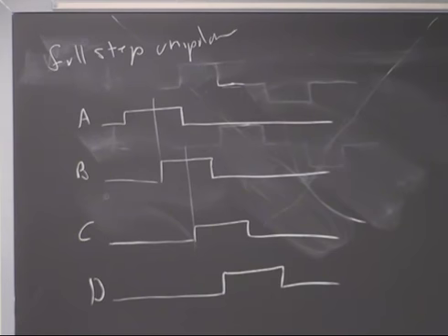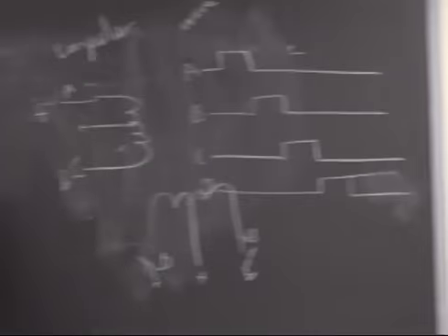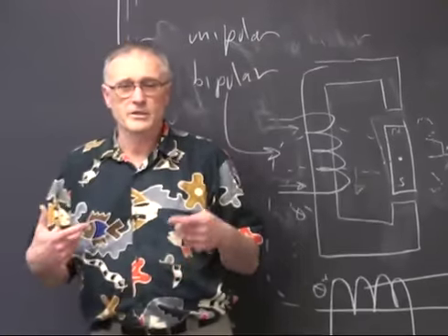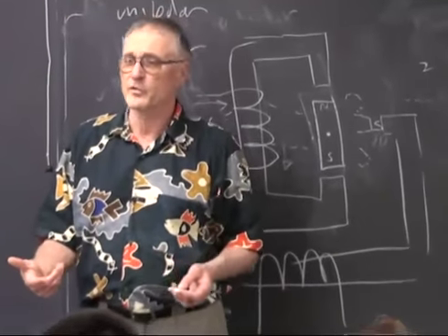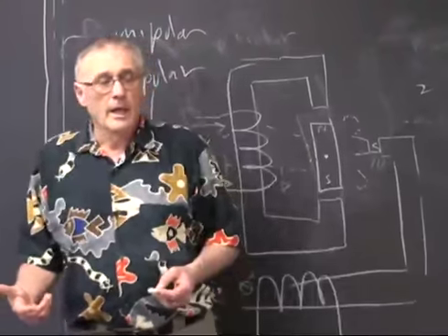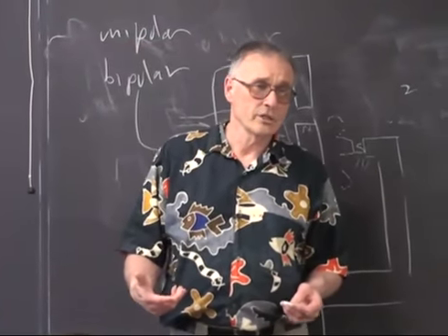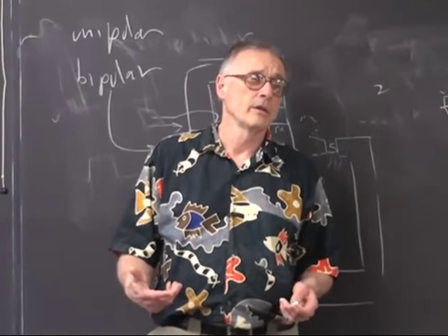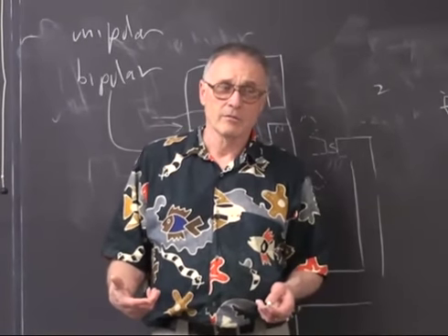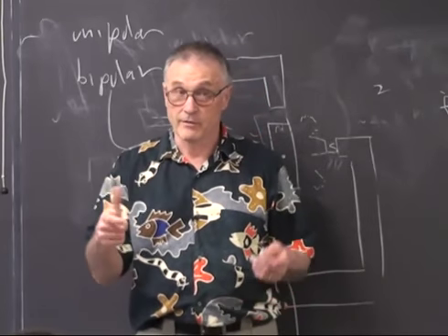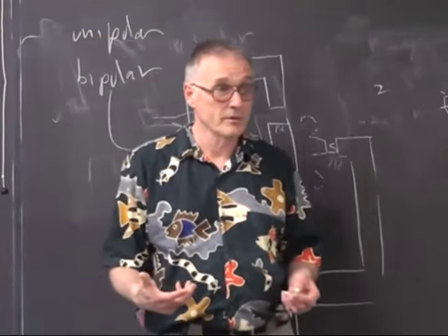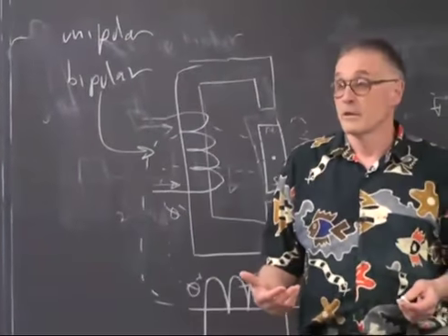So how do you drive these things? Well, again, I would not build an H-bridge. There's a couple of reasons. One is you actually need more than 4 transistors because you have to do level translation. And you may have to do isolation depending on how bad the noise is. You can buy packages which are isolated level shifted H bridges, but you can certainly buy them that are just level shifted and ready to go.